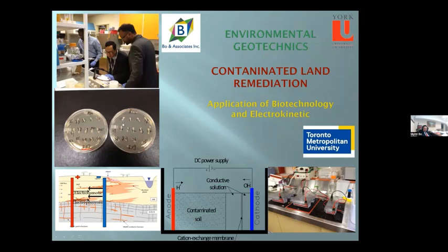Not only did we look for bacteria which can eat the diesel, because their life is short, and their ability to migrate is very slow and limited in distance. So we transported these bacteria by applying the electroosmosis flow from the cathode to the anode, so that they can travel a longer distance at a faster speed. Not only that, we also transported the nutrition behind them so that they can eat it to extend their life.